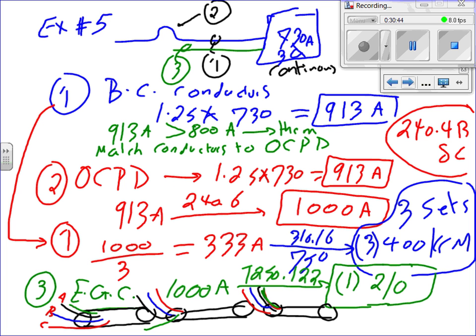The largest conduit that you can get in EMT, which is the most common, is 4 inches. You have to check. Go check if you can fit 9 conductors, 400 kcmil plus a 1 conductor 2 aught, if you put them all in one conduit. Number 1, number 2, it's a nightmare to pull 9 conductors.